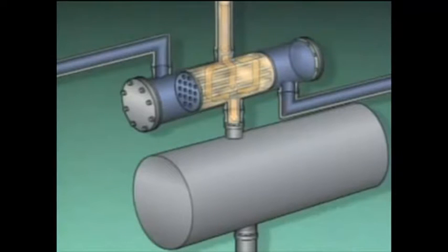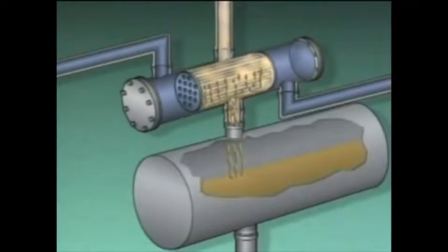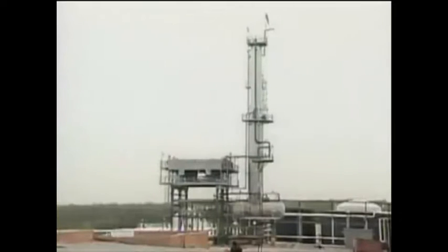A condenser can also be classified by the role it plays in a distillation system. For example, a condenser that condenses all of the vapors from a distillation tower may be called a total condenser. A condenser that condenses most but not all of the vapors from a tower can be called a partial condenser. In this topic, we looked at some of the reboilers and condensers used in distillation systems. Now try some practice questions that relate to this material.